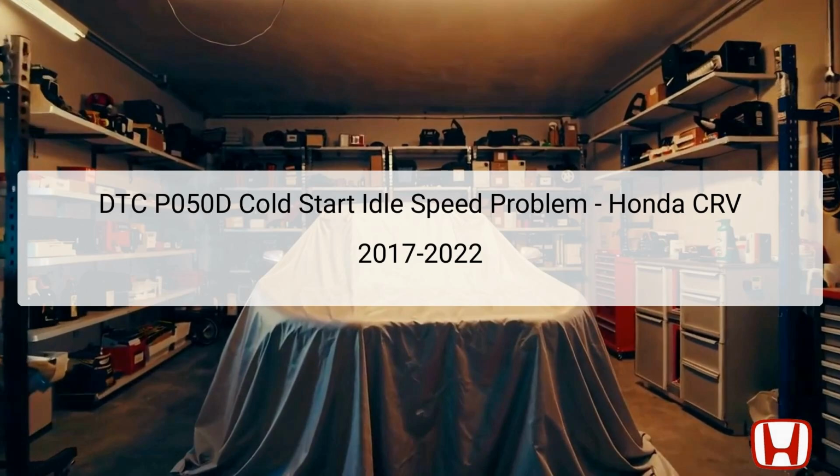The DTC P050D indicates a cold start idle speed problem in the Honda CRV models from 2017 to 2022. This diagnostic trouble code affects the Powertrain Control Module, PCM, and the engine's idle behavior during cold starts. It is crucial for the PCM to receive accurate data from several sensors, including the engine coolant temperature, ECT sensor, and the mass airflow, MAF sensor, to maintain optimal idle speed.